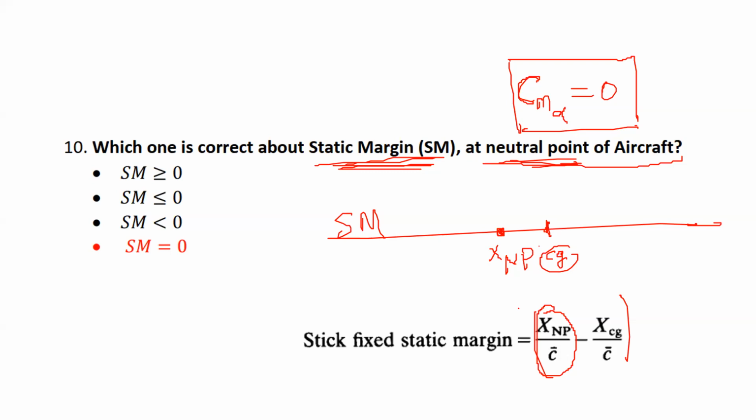So neutral point comes from aerodynamics. Once you have an aircraft, you have a neutral point that is fixed aerodynamically. It doesn't change if you change the amount of fuel in the wings, but CG changes along the flight. So when CG changes, the stability characteristics should not change too much. You want a margin for that. It is guaranteed that CG will change when aircraft flies, and we want to make sure that stability characteristics do not change too much. They will change definitely, but not too much.